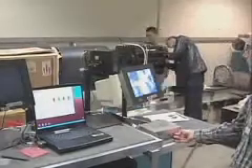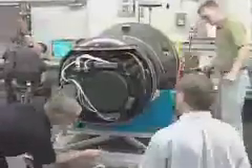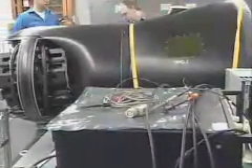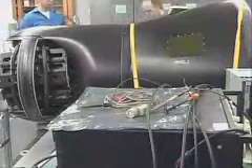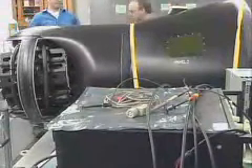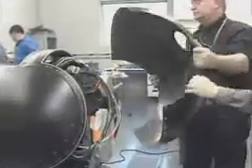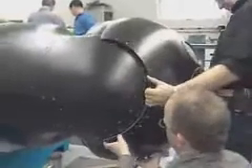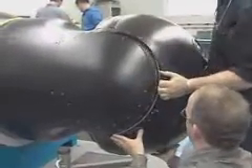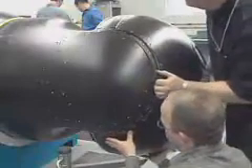The WAVE consists of a ball turret mounted on the nose of the aircraft. Each turret contains an HDTV, a near-infrared camera sharing the same optics. It also has a gimbal segment and all the associated electronics. And since the camera has such a big telescope on it, it also flies a standard definition video camera just to help capture the shuttle when it lifts off so we can get oriented and located on the shuttle itself. The cameras are controlled by an operator back in the aircraft. They can either manually control it or put it on auto track of the shuttle itself.